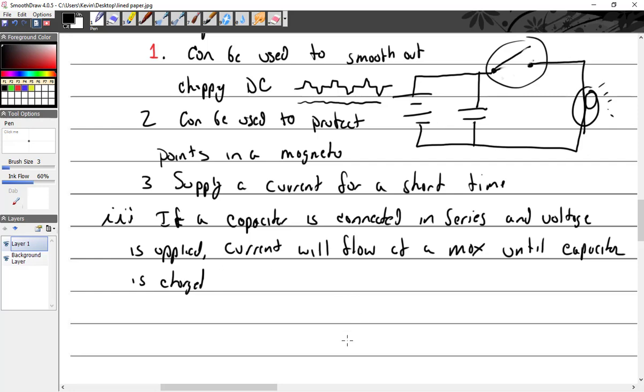Okay, so very little voltage in a circuit with capacitors will have a large amount of current flow. Which is to say, if I look at something AC, and there's my AC sine wave, and we'll start right here at 0, I have barely any voltage going right there. When is my current going to be at the maximum?